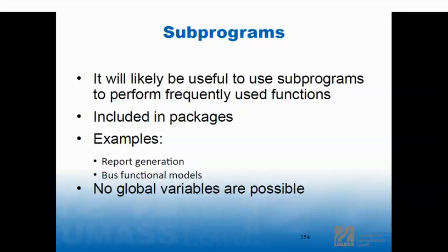And whatever makes sense. You don't want to have a lot of structure here, a lot of hierarchy. You want to keep it fairly thin, but the bus functional models are always there. The test cases are always there. If stuff gets complicated, you might do things to bring that middle piece to a higher level of abstraction. So there's bus functional models.